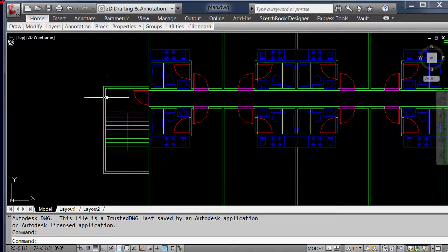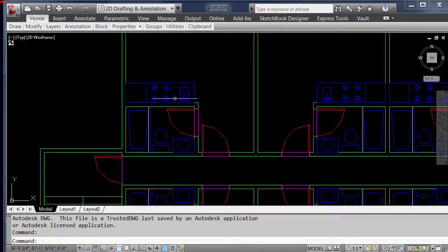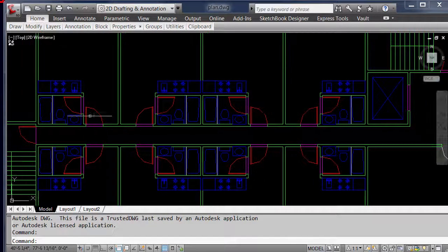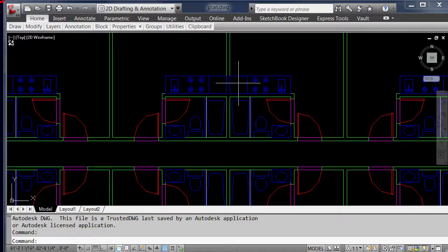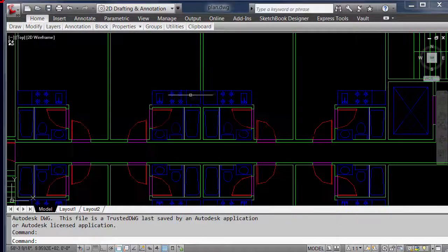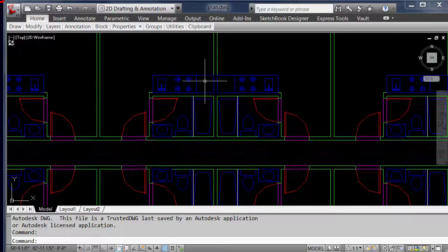If I was looking at a professional plot of this, I would see that the outside lines were a little bolder than some of the elements on the inside. So this might be just a hair lighter, and the door might be bold, depending on the convention of your employer. This is an architectural drawing, so usually there's a convention that they already use.